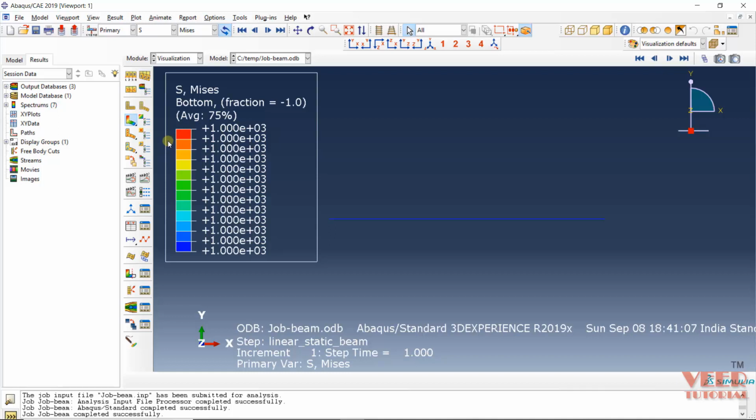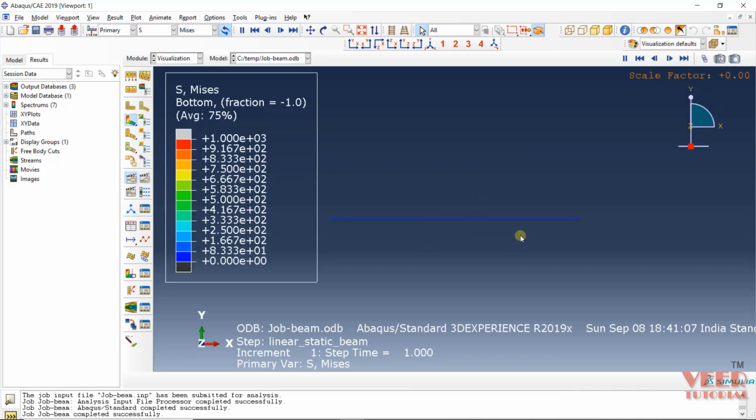And then if we want to see how this beam is going to expand, we can view the animation of the simulation. Below we can find the option of animate scale factor. So click on this option. And now it is going to show the animation, how this beam is going to expand. Okay, we are going to apply this force in the right direction. So this beam is going to stretch like this. I am selecting animate harmonic option. Okay, now it is showing step by step.